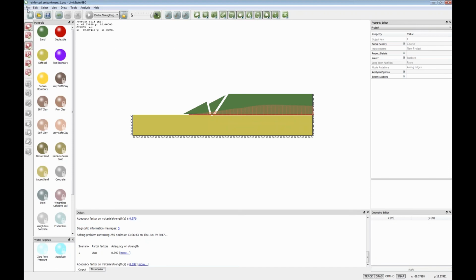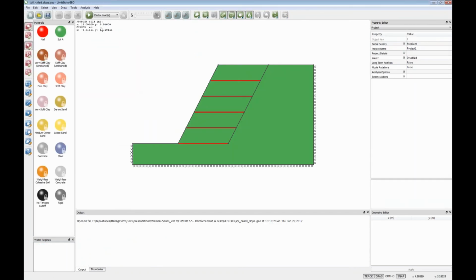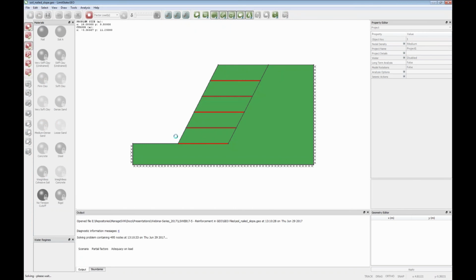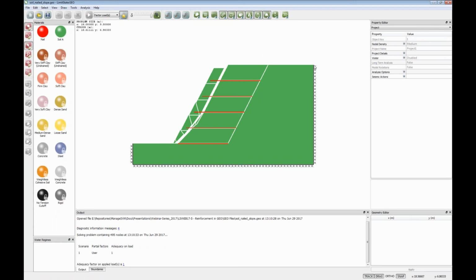and if I pull up one of the other models, let's try the slope. In this case, the reinforcement doesn't touch the boundaries, but if the slip lines did touch a boundary out at one corner, generally that means your boundaries are too close. If they're just artificial boundaries, so this back boundary on the model here is artificial, we're not assuming that there's a wall of rock here. Essentially, we assume that normally you're going to have more soil of the same type behind. So yeah, if the slip lines touch the boundary, that means you need to extend that.